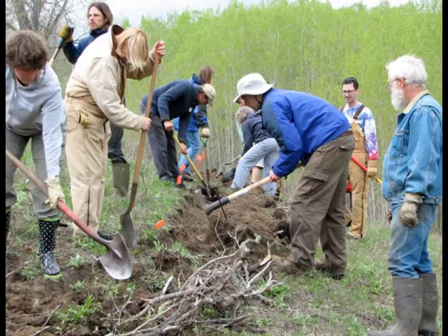This is that one where I showed the orange flags that appeared to go uphill. See that line right there? Is that going uphill, downhill? We're perfectly on contour. It looks like it's going uphill, doesn't it? It's going downhill at a 1% slope. And when you put these systems in the ground like that and you watch the water go, it looks like it goes uphill.